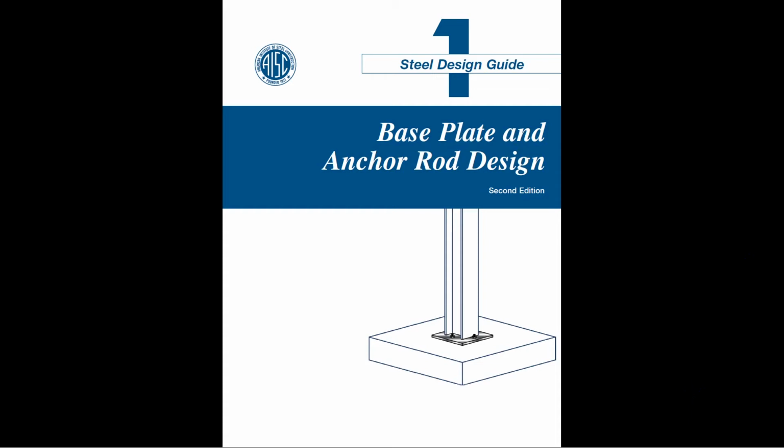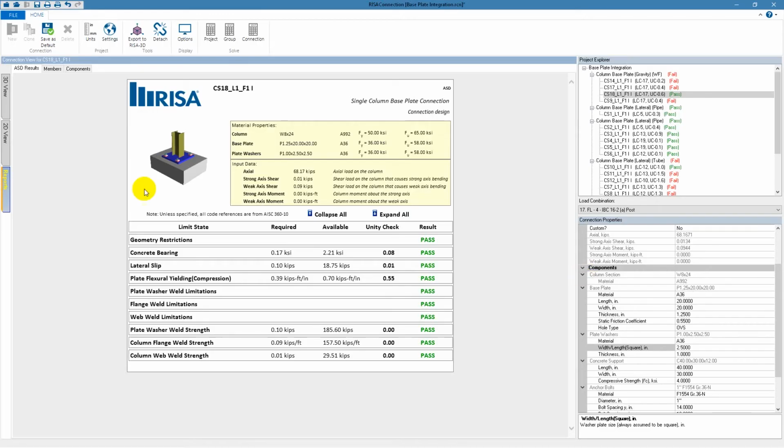The one edit to that, or the one revision that we've added in order to account for biaxial bending in both directions at the same time, is we're taking into account some design references per the AISC Engineering Journal article called Two-Way Bending of Base Plates under Uniaxial Moment Loading, Alternative Approach. So we implemented the ideas from that paper as well in order to account for biaxial bending.